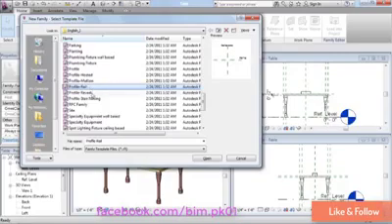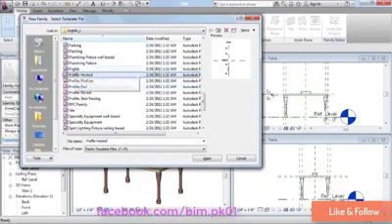This is the one you'd use for a railing, for a stair nosing, and so on. You have 2 choices here for profiles that can be used in more generic situations. A hosted profile is really what you would use if you were creating a wall sweep or a wall reveal. A little difficult to see in the illustration over here, but there's some text on there telling you where the wall would be versus where you would draw your profile. So there's just some little text cues there.